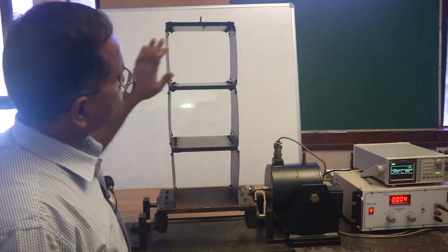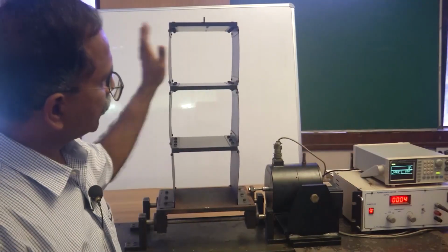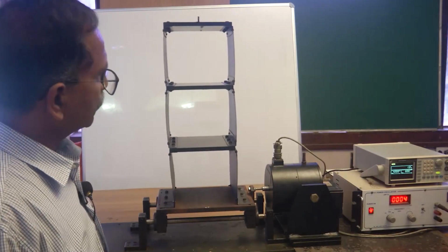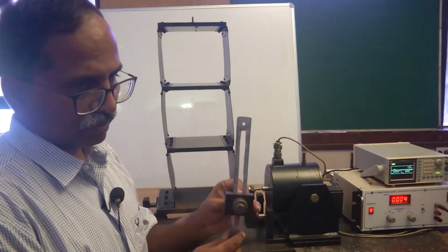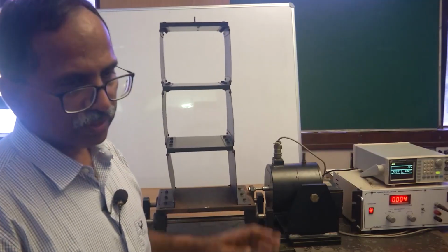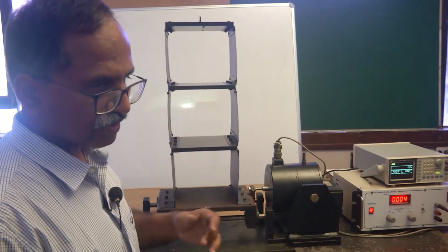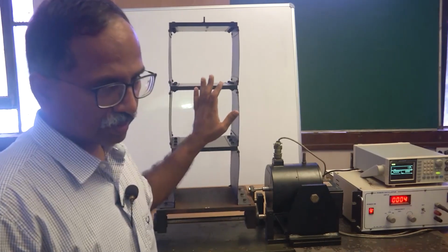Now, if this frequency is 1.3, where large resonant vibrations of this building are being observed, we said that if you attach an auxiliary system, the absorber, which has the natural frequency tuned to the natural frequency of the parent vibratory system, the amplitude of the parent system can be brought to 0.